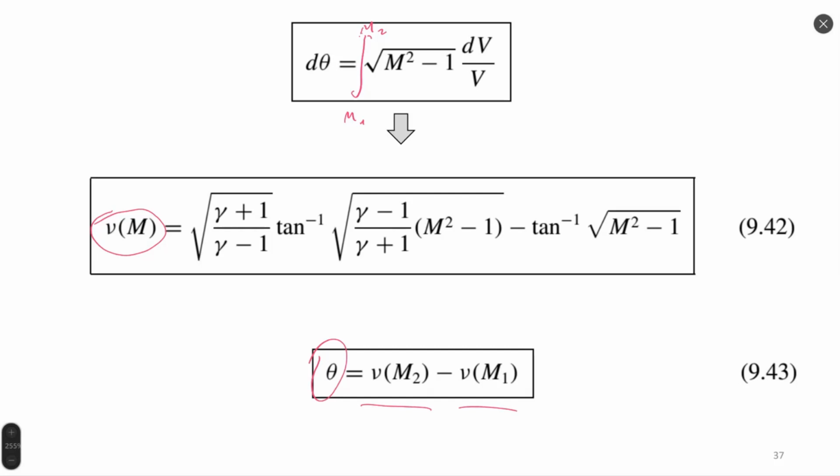The Prandtl-Meyer function is an analytical solution of this equation of differentials, which you can see on the top of the screen. When we analyze the Prandtl-Meyer function, we can see it's purely analytical, involving the trigonometric function of tangent, because the definition of Mach angle involves tangent.